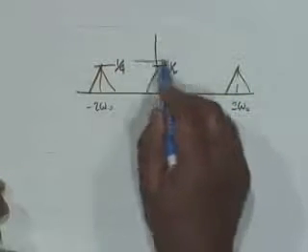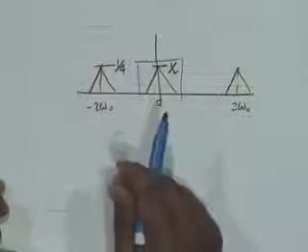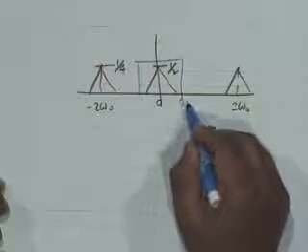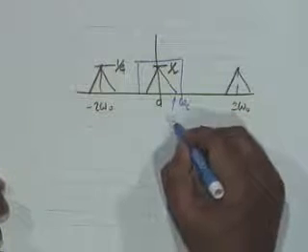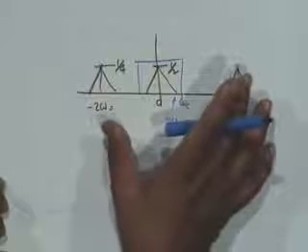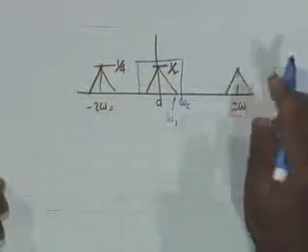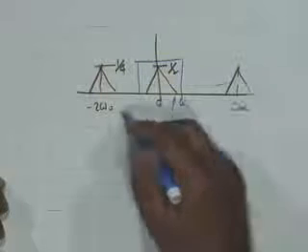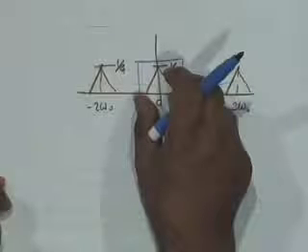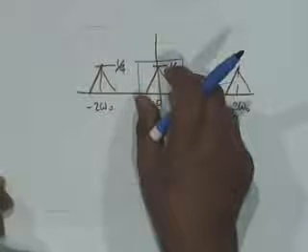So what you have to do is to construct a low pass filter. That is a filter which passes low frequencies, let's say 0 to some value omega c, which is greater than or equal to omega 1. That is, you pass this spectrum through a spectrum window which discards the high frequencies and retains only the low frequencies. And this is what then you amplify in an audio amplifier and enhance the power by means of a power amplifier, put it to the stereo and listen to it.